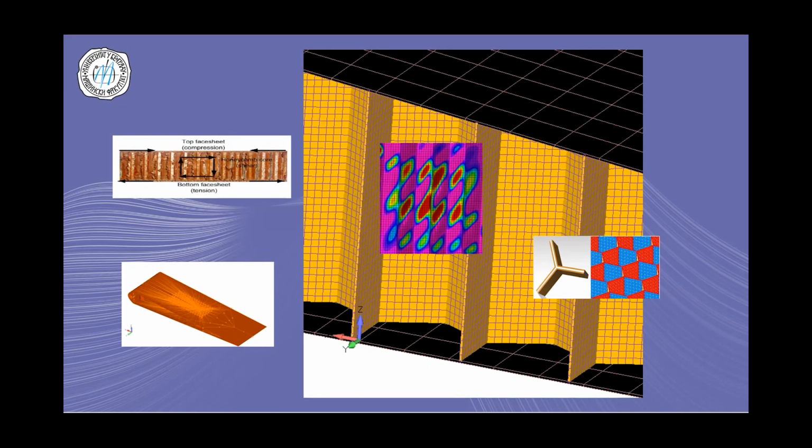Third of all, another problem is that if one accepts this approach of precise modeling at the mesoscale level, one should pay attention to really explore something that we call connections. Because here, first of all, we have incompatible elements: we use 3D elements and plate elements. So this model is full of connections. You can see them here in red. And these are not the blue connections, but rather linear connections, in order for this to work in the realm of dynamic analysis.